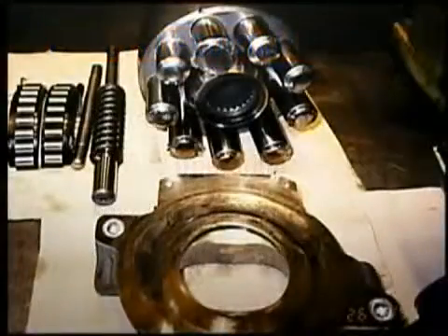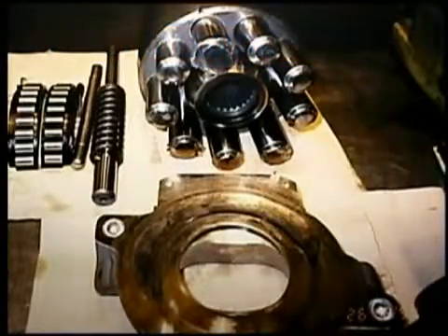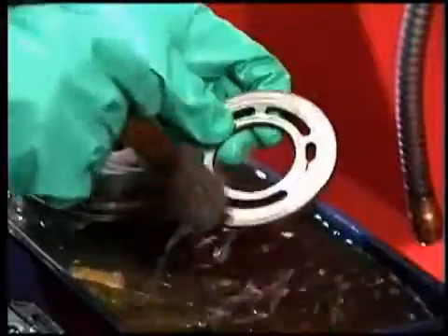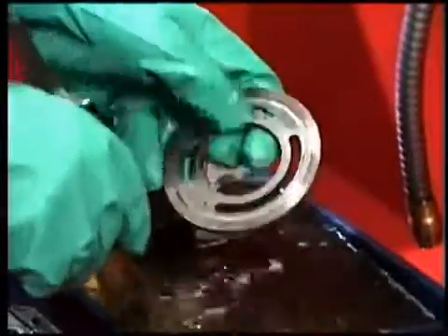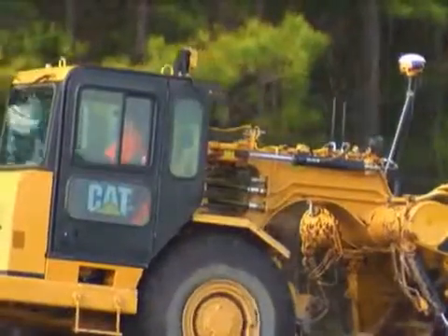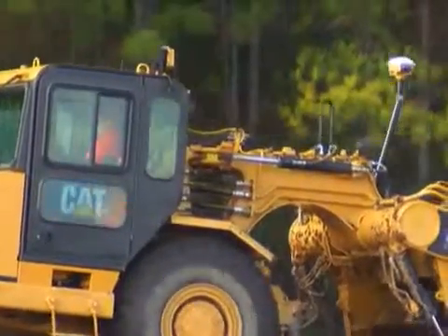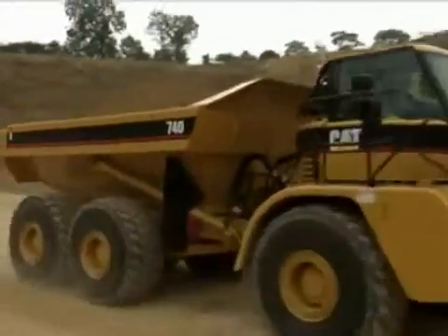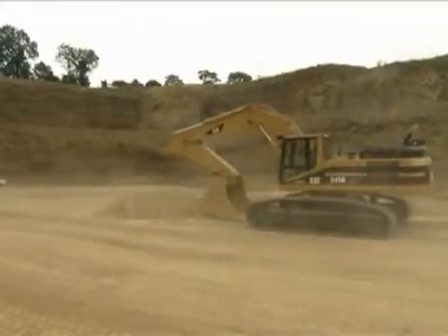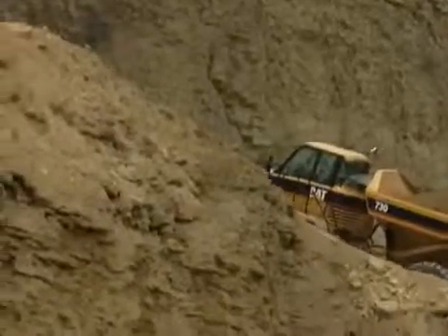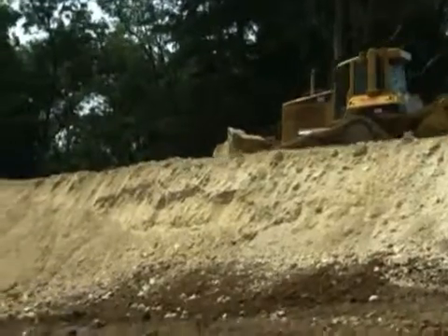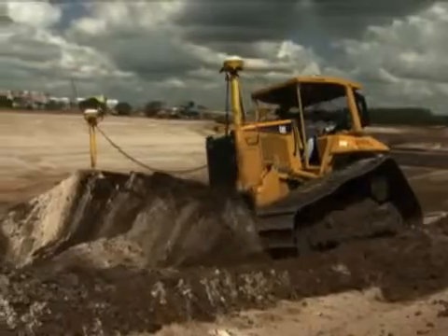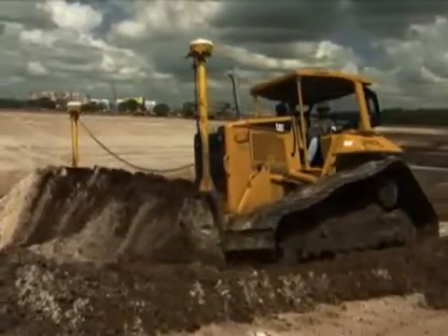The pump is one of the most expensive components to fix in a hydraulic system, and in the event of a catastrophic failure, it may take days or even weeks to repair a contaminated hydraulic system. But contamination harms more than just hydraulic systems. For example, contamination can affect the control valves that regulate the amount of oil going to the clutches in transmissions. Contaminants can make the valves stick or plug the orifices. That will result in harsh shifts or the inability to shift.